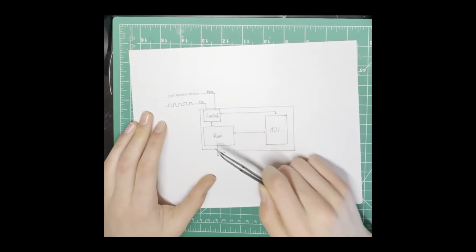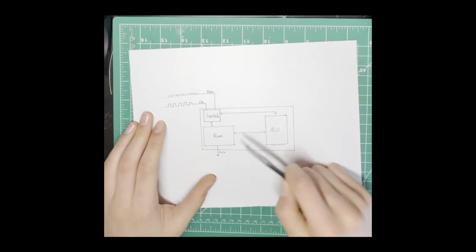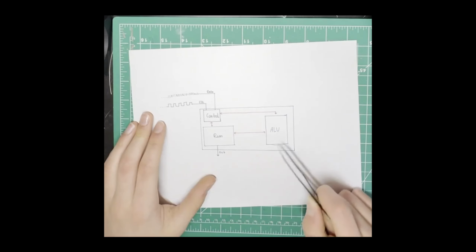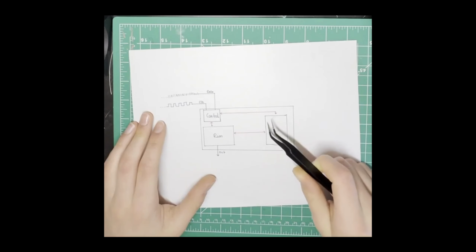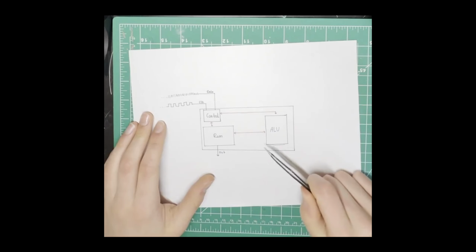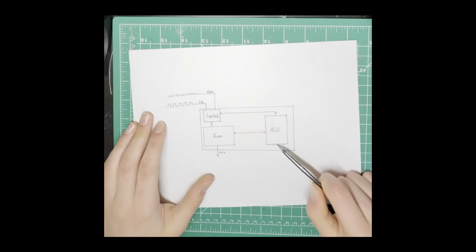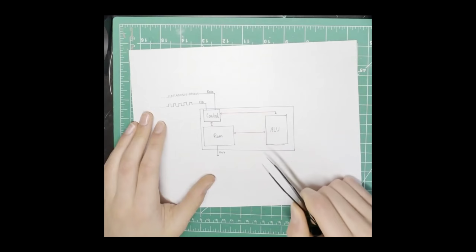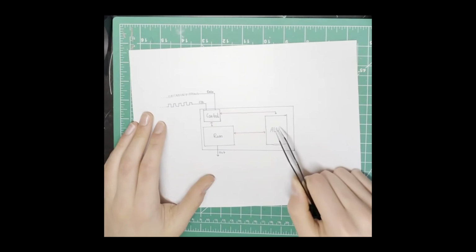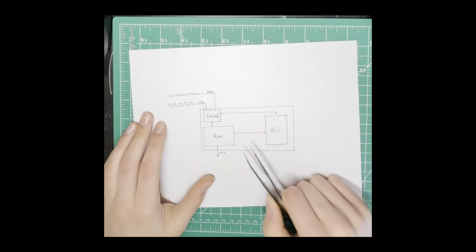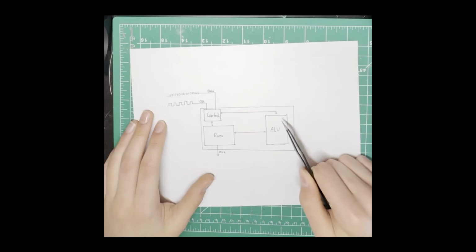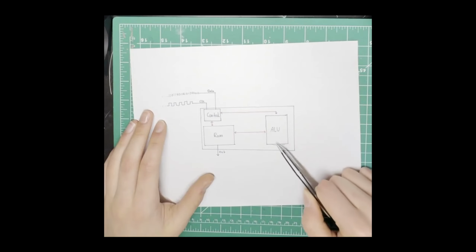Now the 3 blocks inside the CPU are quite simple. Your RAM, your ALU, and your control unit. Inside the ALU, we have 3 registers. We have the A register, B register, and we have our C register. A and B are your 2 operands for the ALU. Your C register is your accumulator, or your output. And the RAM just interacts with those 3 registers. So it reads and writes to A, B, and C registers, and mostly writes to A and B, and mostly reads from the C register.